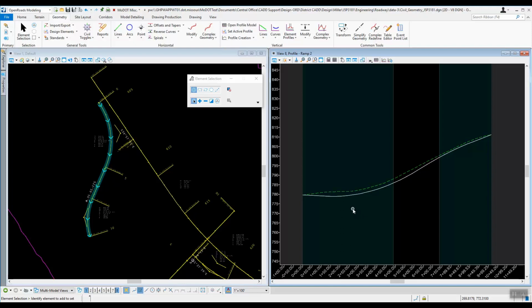The other version that we take a look at would be using Civil Accudraw. Now I'm going to use Civil Accudraw and place it in like we did with exercise number 2 for ramp 4. You could do something similar with Civil Accudraw like we just did with the complex by VPI, where you could give it all this information and have one chain created. But we're going to do this one with the lines and the curves. So I'm going to go ahead and delete this out, and we're going to do it again, but this time we're going to use Civil Accudraw.